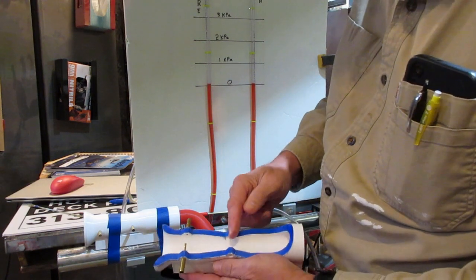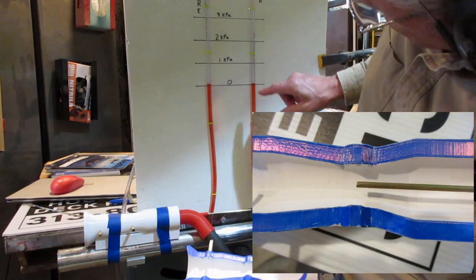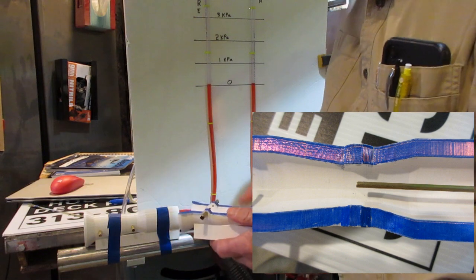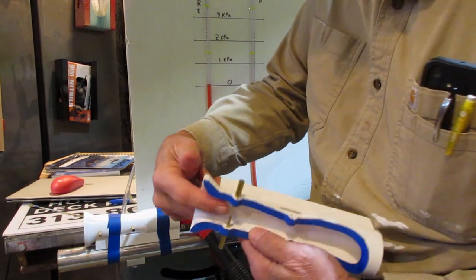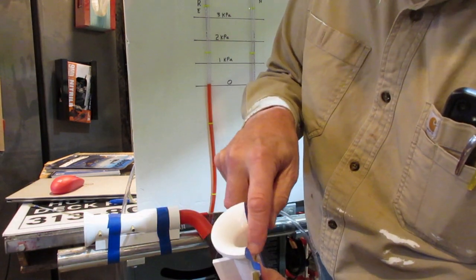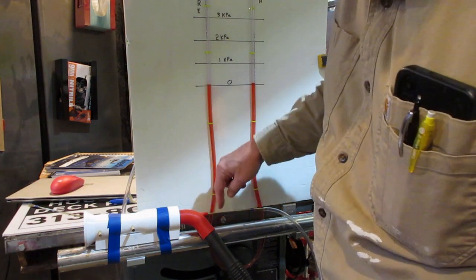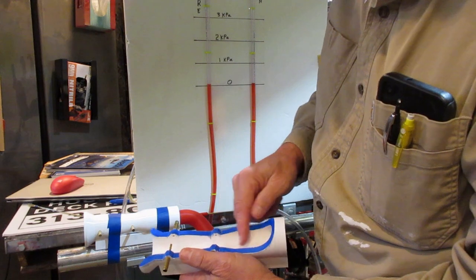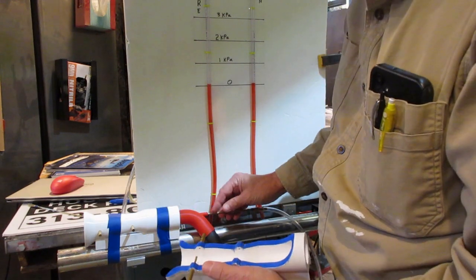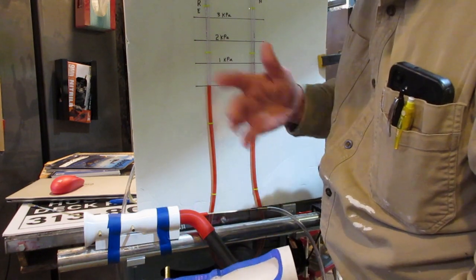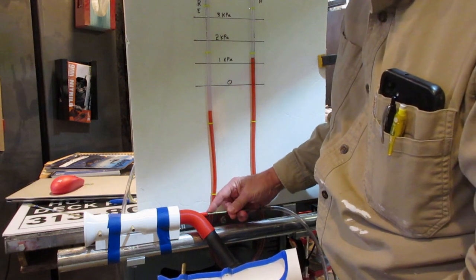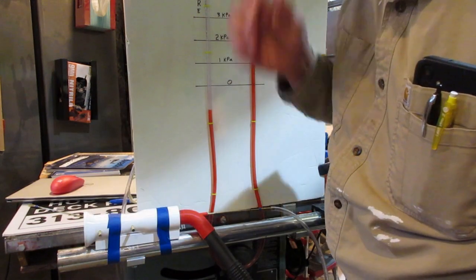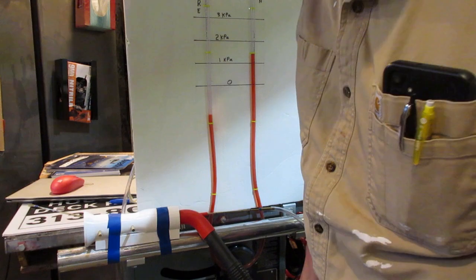Little wobble there. Where the problem is, when we go further back, because that Venturi diverges too rapidly, we get a lot of losses, and then the total pressure goes way down, and at that point basically Bernoulli has left the room because we no longer have our conservation of energy along that streamline. It's just too much turbulence and loss.